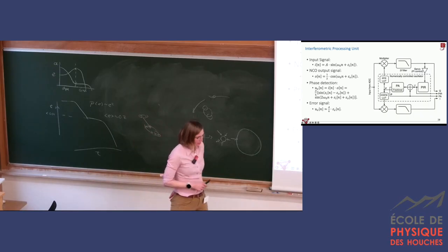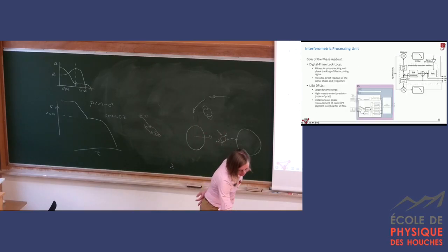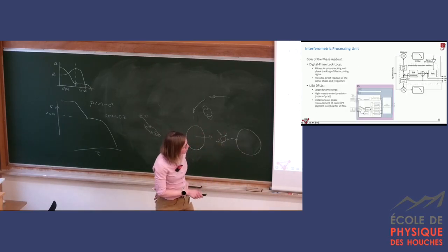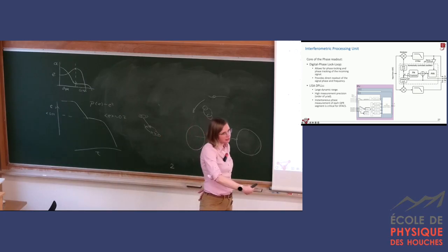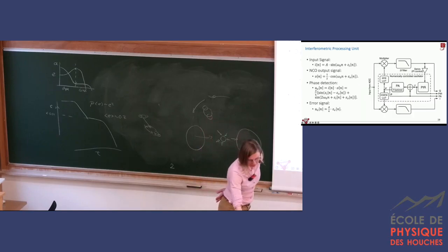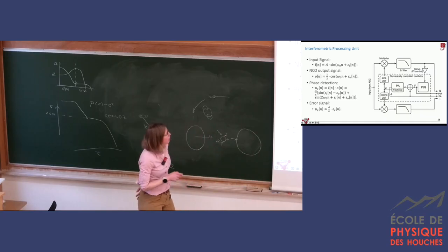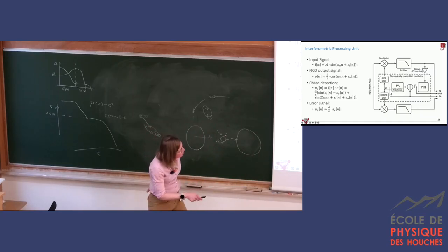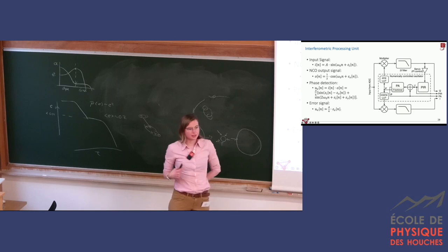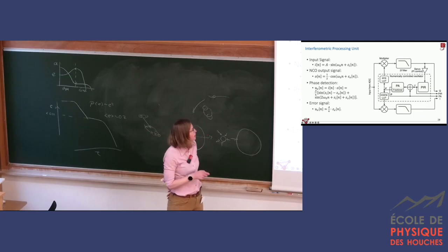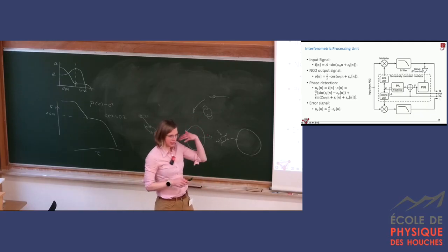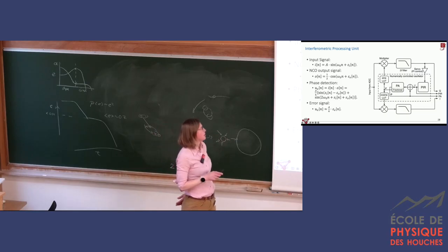So let me jump forward. As I said, at the front here we have the signal conditioning electronics and analog digital converters. They receive the voltage signal and transfer it into digital land from the real voltage land. So our input signal to our phase lock loop can be represented like this. This is the digitized signal.